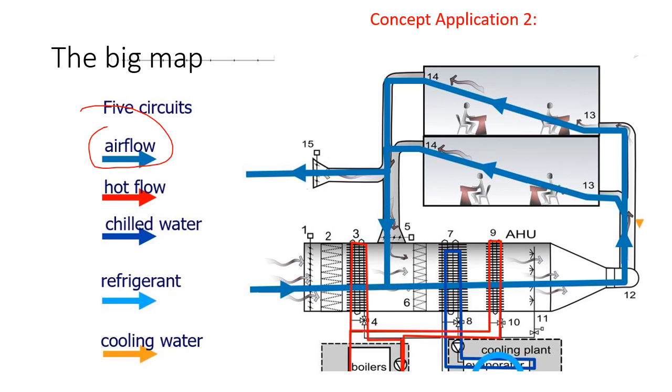The outdoor air mixed with room air goes through this cooling coil, and inside the cooling coil there's chilled water. Chilled water absorbs heat here, and the temperature will be lower. The surface can be lower than the dew point, so not only does the temperature drop, but moisture is also turned into dew and becomes condensate. So at this coil, air loses both sensible heat and latent heat.